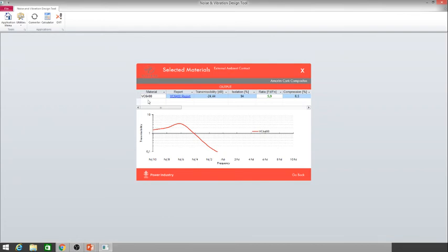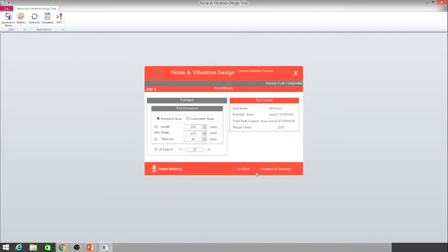Material VC6400, 94% isolation, 60.5% compression on material, and all the information that you can print out and save if needed. But you don't want so many pads, and you want to use fewer pads because on the shop floor you don't want to have so many small pads.